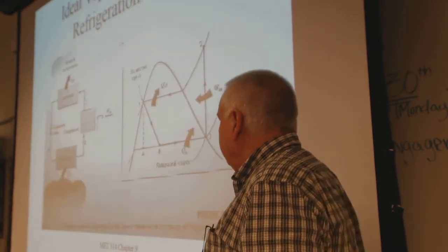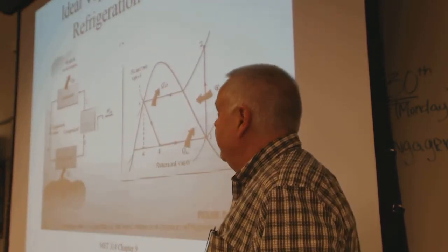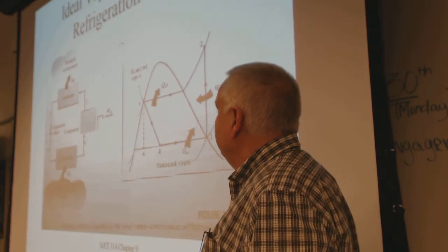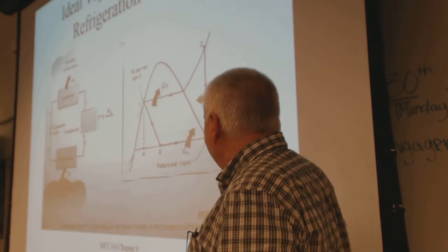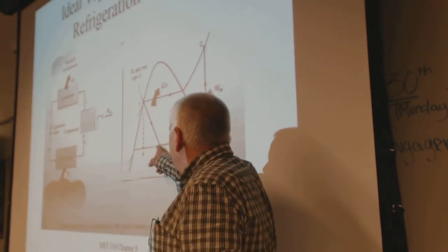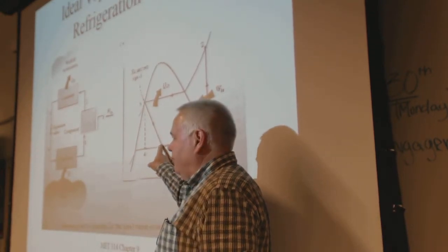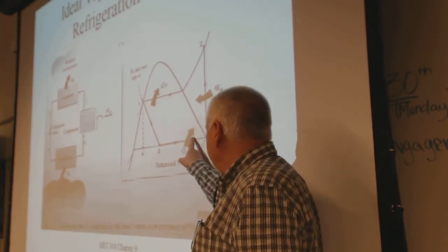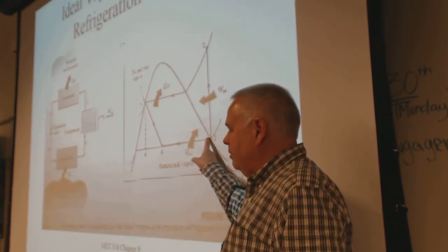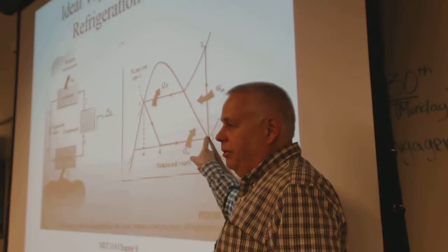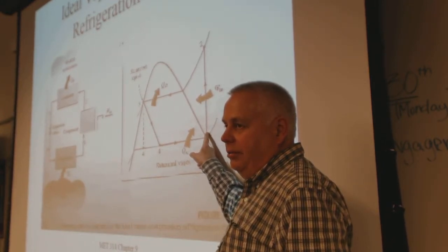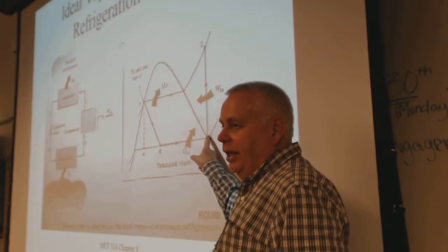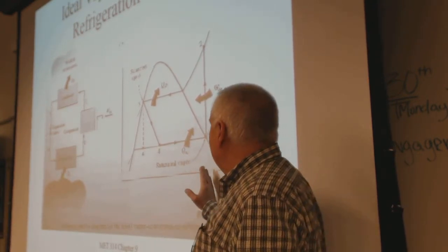So it's the Rankine cycle in reverse. They literally call it the reverse Rankine cycle. It's a vapor compression refrigeration cycle. In this case, we get a fog, and we evaporate it in the evaporator. That's the cold side, to the point where it's saturated vapor, or even maybe superheated a little bit at low temperature. And then we compress it isentropically.